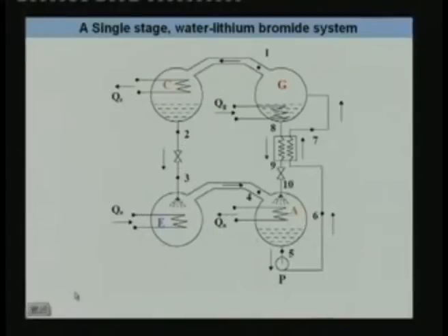So what we will be doing is applying a steady state steady flow analysis to this system to arrive at expressions for COP, mass flow rate, etc. Typically, in a steady state steady flow analysis for any refrigeration system, we take a control volume across each component and apply mass and energy balance for each component. Then you get a set of equations, you supply the required number of inputs, and you get the output when you get the properties from your inputs.